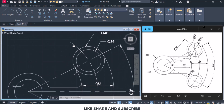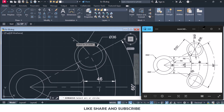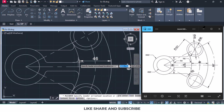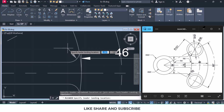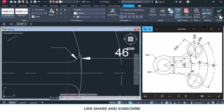For this also we can use radius and click over here, and radius is 101. Now for here, we'll use this again leader dimensioning. Click over here and give the radius as 6 units and close the text editor.